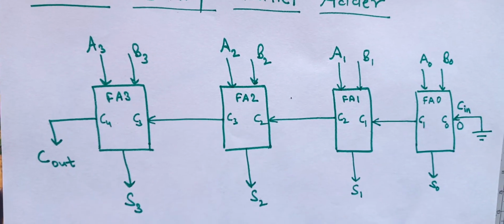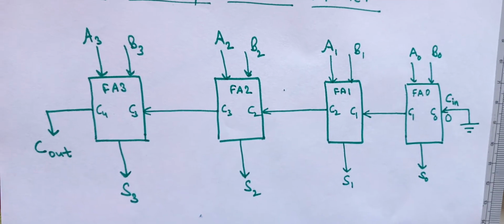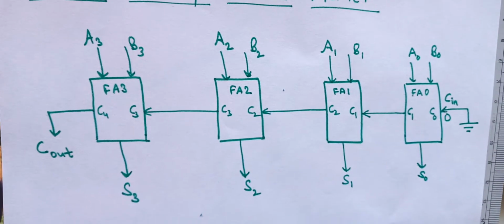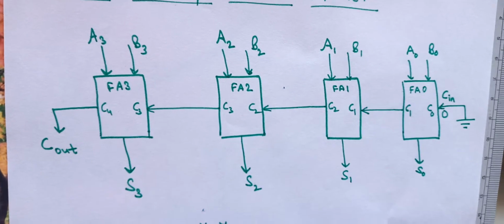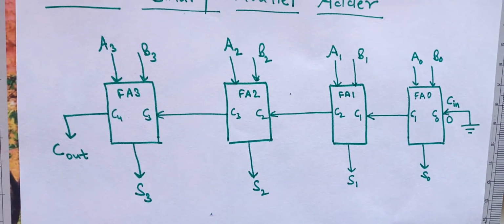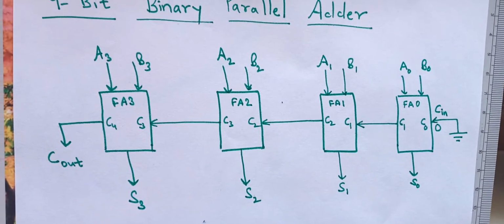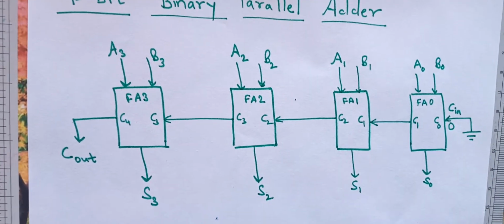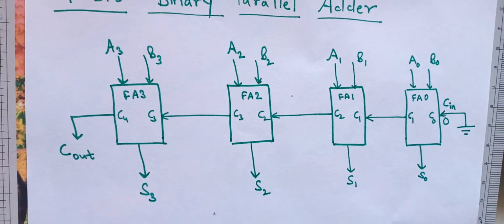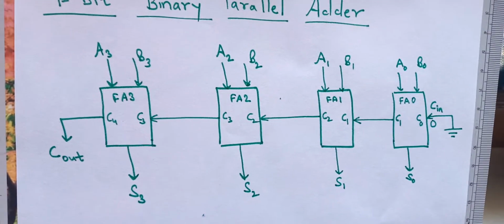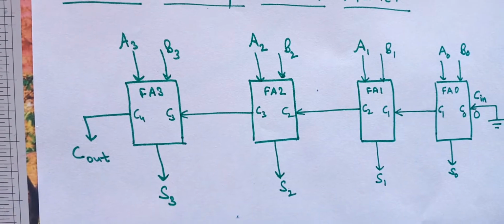This is the connection diagram inside this IC, and also we know that full adder is made from basic gates. So inside each full adder, basic gates are involved. For each full adder, we know that the sum is the XORing of the 3 inputs, and also we know the carry output, which is XY plus YZ plus ZX. So let us say FA3. What is inbuilt in FA3?